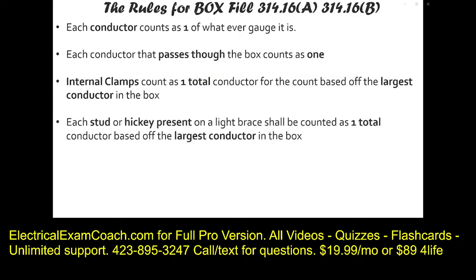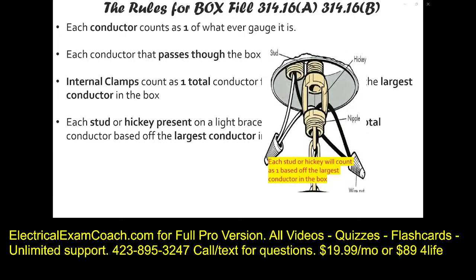Next, each stud or hickey that is present in the box shall count as 1 total based off the largest conductor that's in the box. Now, these are really old words, probably from the 30s if I had to imagine, but they still use them on examinations today. And this is what we're talking about. Imagine that we're hanging a chandelier. This we would call the stud or the nipple. Or, this would be the nipple. But they're calling this the stud and this a hickey. And they still use this terminology on exams today, so you definitely need to understand.